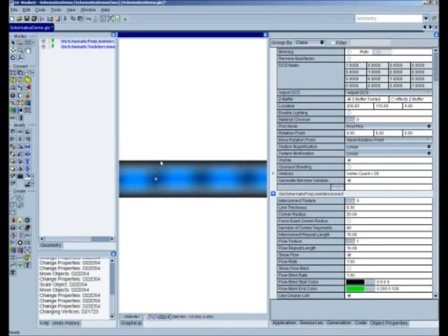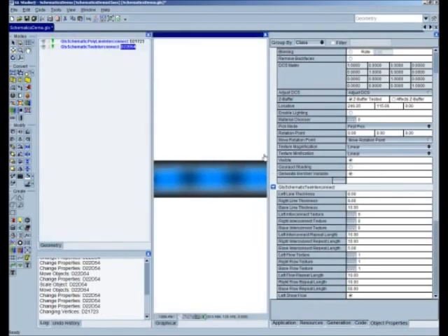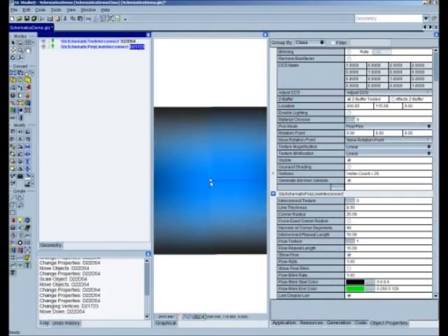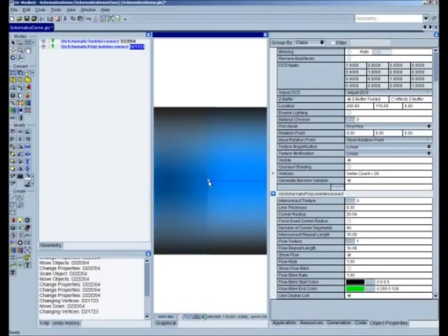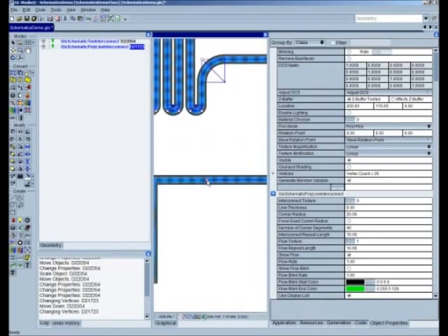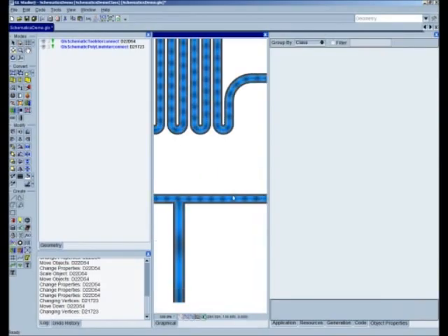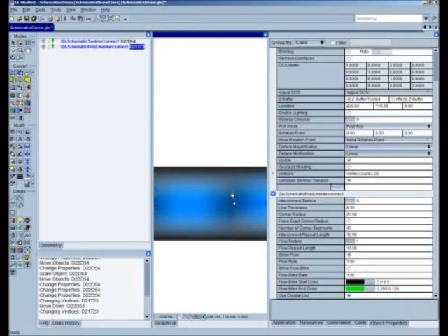Now, in the last little joint we see a little bit of white. That's actually the end of the T interconnect with the polyline extending behind it. If we put the polyline in front, that should go away. So we'll select the T interconnect and send that to the back. Looks like we're going to have to do a little bit more tinkering, but we can already see a noticeable difference. It takes a little bit of lining up to make it work, but once you've done that, the end result is that this will go away.